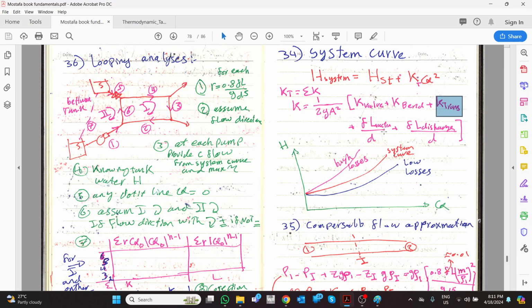You need to count it all, sigma, count each bend, each valve, and the total friction coefficient divided by D multiplied by the length of that pipe plus the other pipes. Of course, you will take the longest run when you calculate all the Ks.